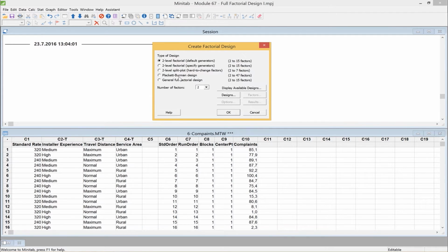A Plackett-Burman design is where you're just trying to sort out whether any of these factors matter. Again, those are two-level designs. They're very bold in terms of how you choose the low and the high at the limits of performance. And the idea is if there's no variation seen across the low to high on a factor, it's not significant, and we can eliminate it. And then the general full factorial design is a factorial design that we can use, but it has its own approach.